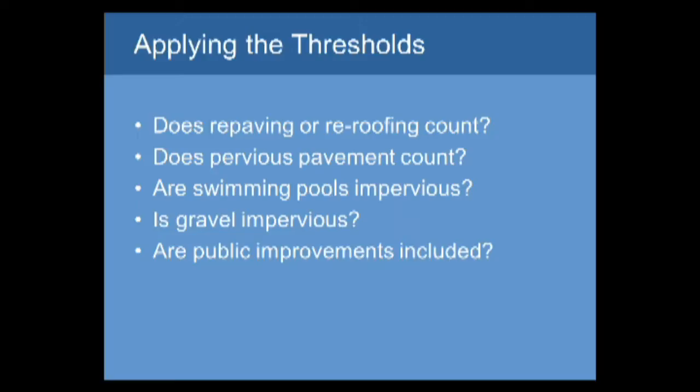Are public improvements included? I don't know whether this happens here. Situation: the developer comes in, has a private property that they're going to develop, and then the city or the governing agency requires them, as a condition of that, to also pave the currently dirt or gravel street in front of the property. So now their impervious area for their project goes much bigger. And I think the expectation there is that no, that is one project. In all of the other reviews that you do for CEQA or whatever, you're considering that as one project because it's a project requirement. And yes, that additional impervious area counts towards the threshold.